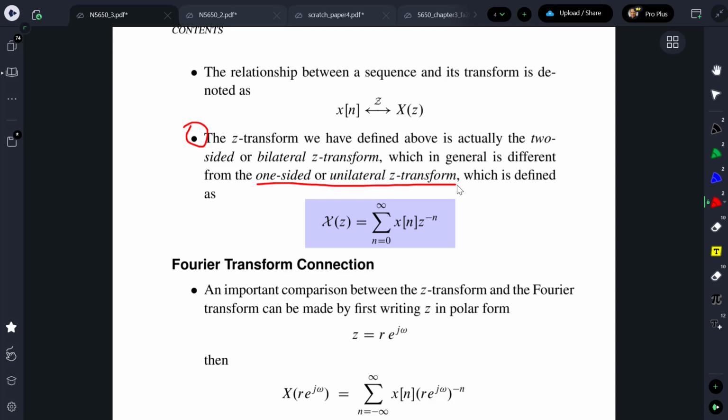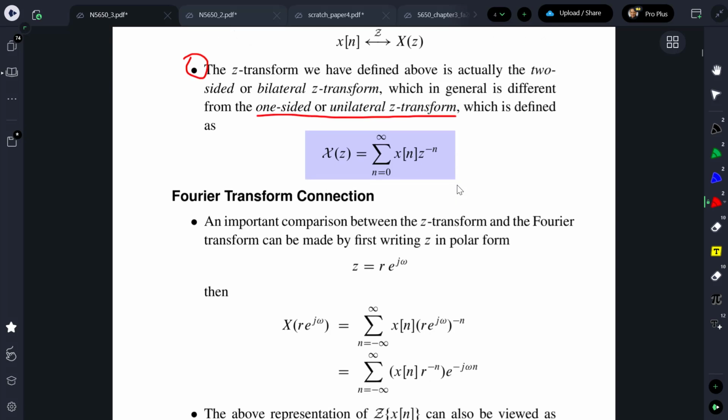And the reason why the two-sided Z-transform is so dominant is because it relates to the Fourier transform of a sequence, which ran from minus to plus infinity in the sum, very well. And it also deals with the fact that in the discrete time domain, we're abstracted into working on a computer where we might be having signals running backwards or forwards. So we have signals that can start at a point and go backwards, or we can start at a point and go forward. So I think the authors of this book, way back in '65, when they were the pioneers of the first discrete time signals book, said this has to be, and even though they revised the book many times, it hasn't gone away. It just stays here, and it's going to get embedded in your brain now too.